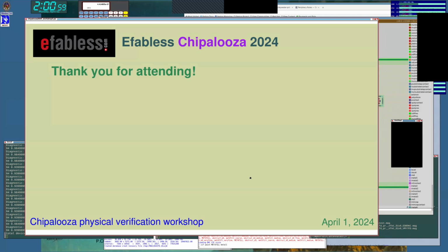Next one is: is it possible to do R plus C and R plus C plus coupling capacitors with a Magic extraction? And I knew how to do the last one, that's option 3. Question is, can you do R plus C only as part of the Magic extraction flow with your options today? Yes, you can. I didn't mention this in the talk, but to separate the coupling capacitance from the substrate capacitance, it's done in the extract command. So you need to look that up in the extract command reference in Magic. I believe it's extract no coupling, maybe. Look it up, but you can separate all 3 of those, yes.